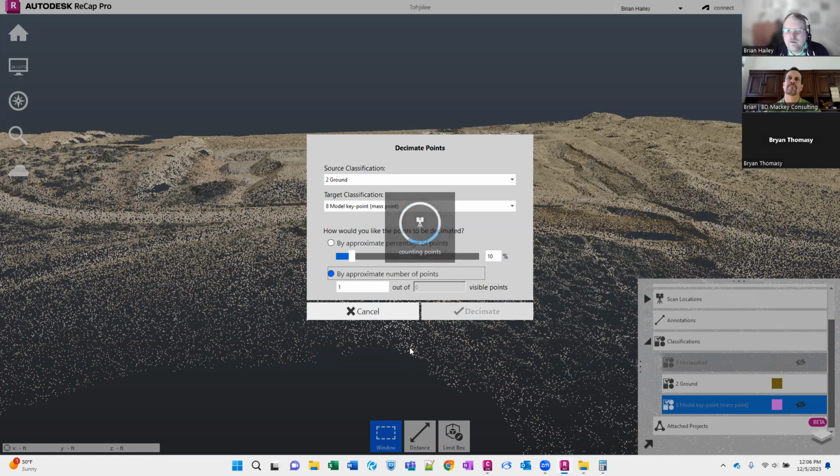It'd be nice if it could actually segregate based on angle of slope. It does. So you can get more points over sloped areas than non. And it's not the angle of the slope, it's how varied it is. If it's a plane, even though it's really steep, you only need 4 points to find that plane, if it's consistent throughout.